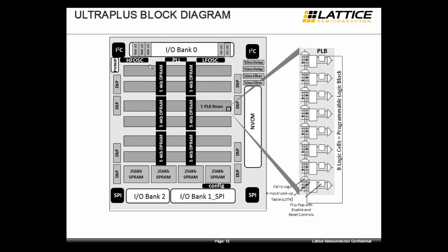There are various I/O banks available in this device, and as a matter of fact, there's 3 I/O banks available, banks 1, 2, and 0. Each one of these banks can be connected through an external VCC I/O pin to a voltage between 1.8 to 3.3 volts. So each bank can operate at a different voltage. Hence, the IOs can be hooked up to those type of interfaces.